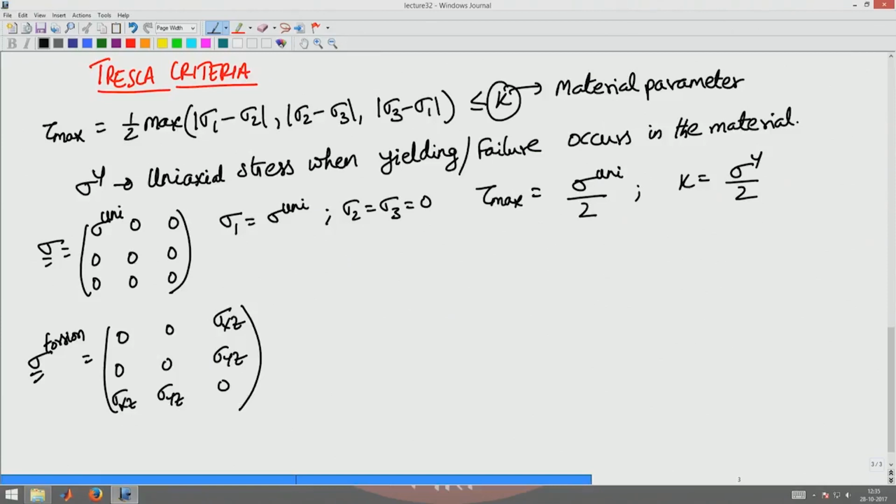In particular, if I am interested in a point where the shear stress acts parallel to the y axis, for example at a point along the x axis, then sigma xz goes to 0 and I will have only sigma yz. Let me say this is tau, the magnitude of the shear stress acting at that location. So, I have a state of stress which is pure shear.